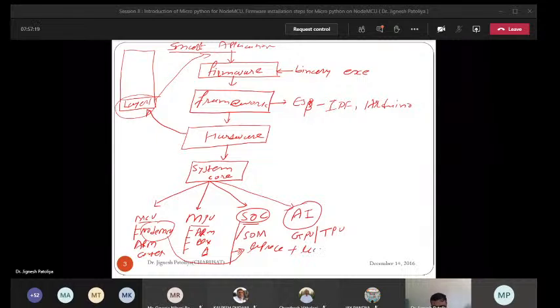or microcontroller plus some connectivity, either BLE, Wi-Fi, or Ethernet. If all these are integrated in a single chip, then we can announce it as my SoC. Now what is called system on module? If we integrate memory and some peripherals with this module, then it is called a system on module.